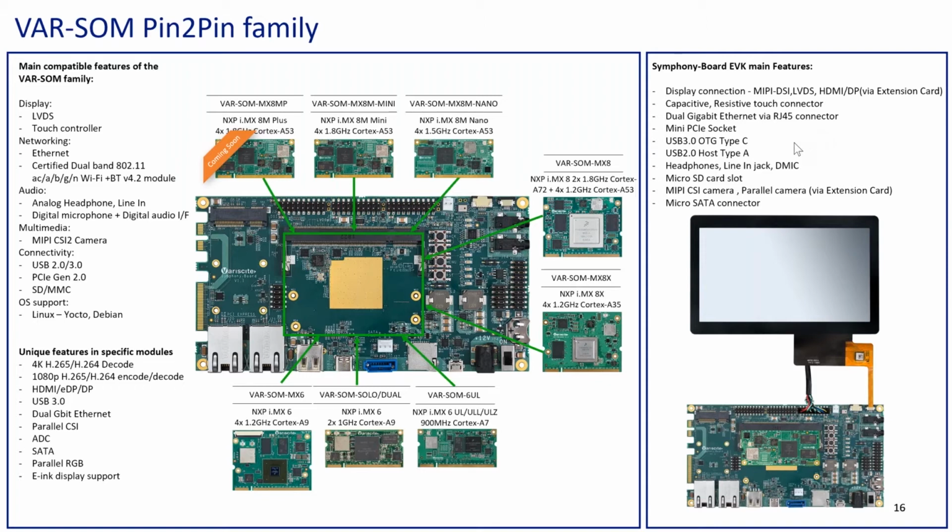So there are 2 pin-to-pin families. The first is the Dart MX 8M family, and the other is the Varsome pin-to-pin family. We will be focusing on the Varsome pin-to-pin family. The family members are starting from Variscite's mature Varsom MX6 and its subsidiary, the Varsom Solo Dual SOMs, going through the Varsom 6 UL based on the i.MX 6 UL, and up to the latest family of processors, the i.MX 8 and the i.MX 8M families. All of these SOMs connect using a SODIMM 200 pin connector.